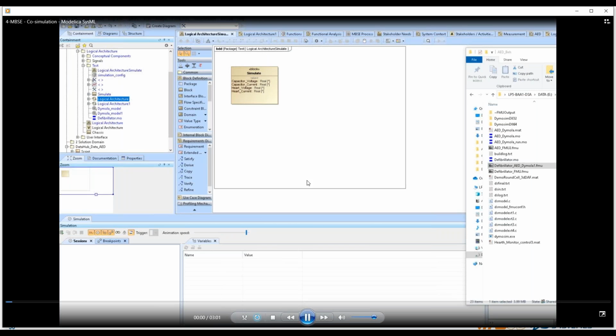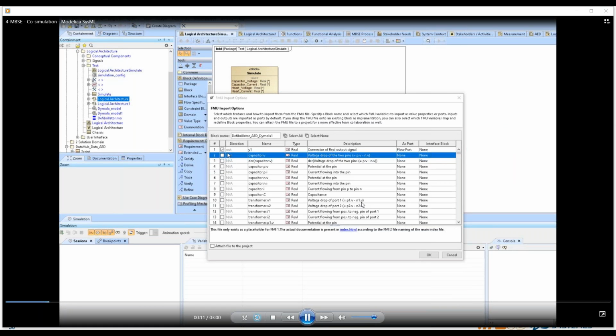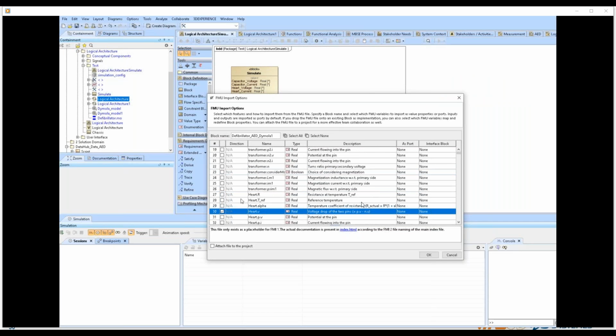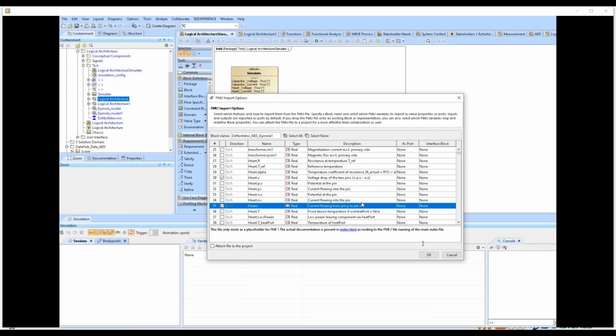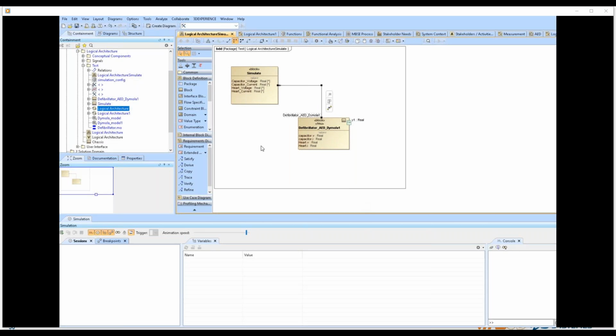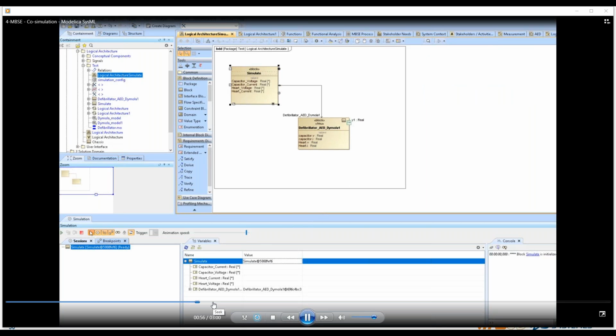And now with the SysML model that you are using for high-level requirements, you are able to import your simulation model that I explained to you, like Dymola or MATLAB models. All of these you can generate as an interface, and you can bring this model into Cameo Systems Modeler for modeling the SysML model or system model for MBSE. And you can develop co-simulation or simulation in the MBSE environment.